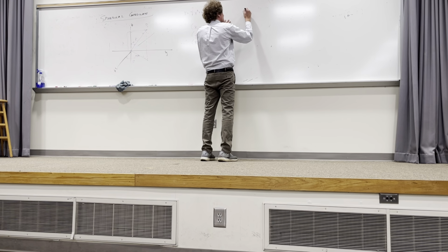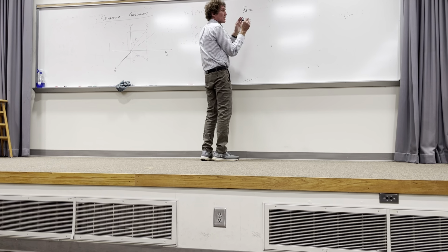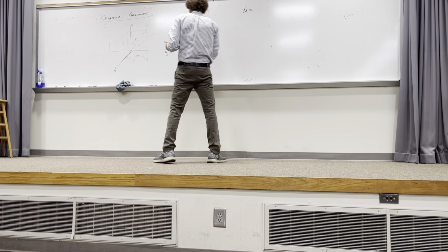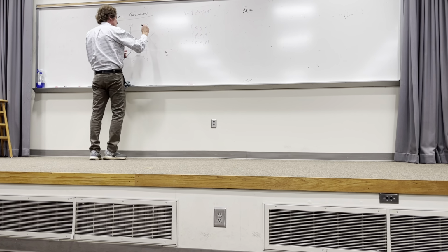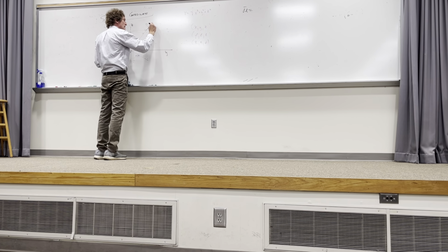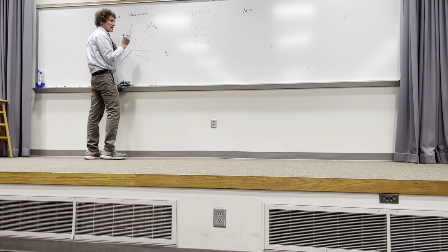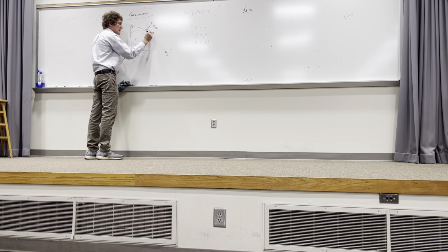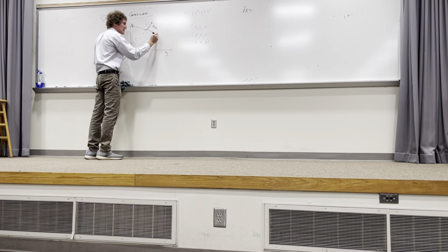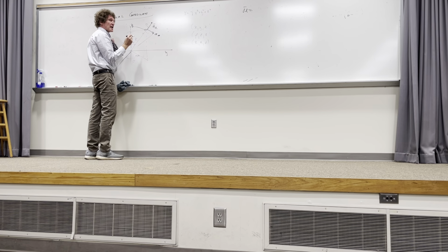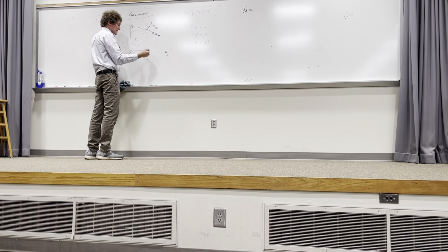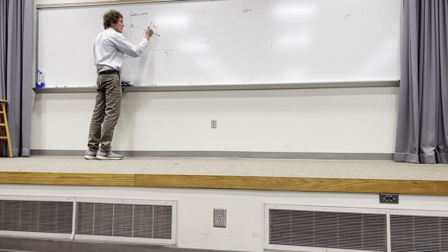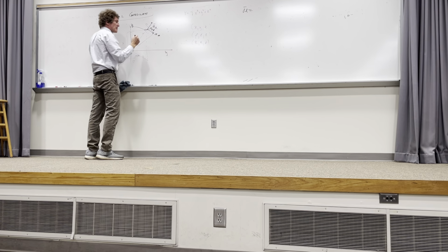When I take a look at differential length, remember you have unit vectors. I didn't actually show you here, but you're going to have a unit vector in the radial direction. That would be A R. Then you're going to have a unit vector in the theta direction, since theta is measured this way, and it would be like this. This would be A theta. And then you're going to have a unit vector in the phi direction. That is going to be pointing into the board and would be A phi. You all follow me on that?